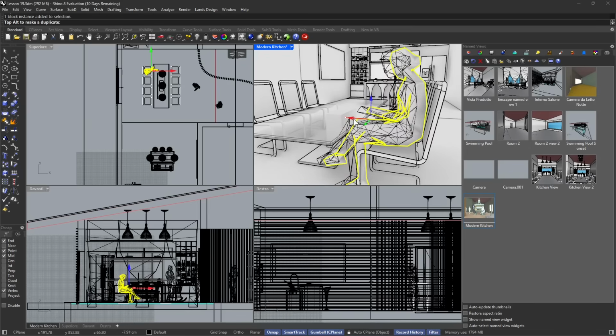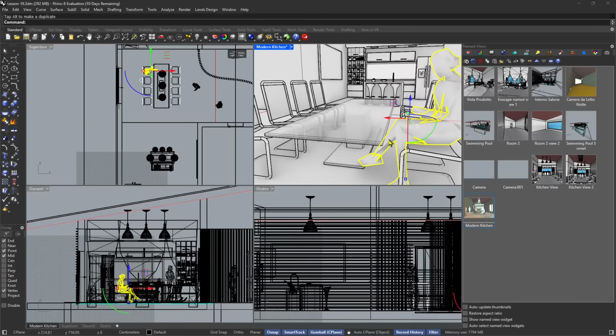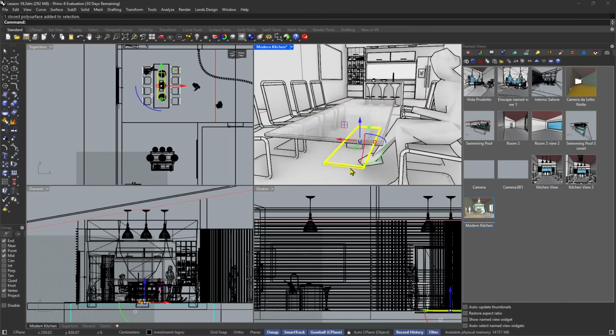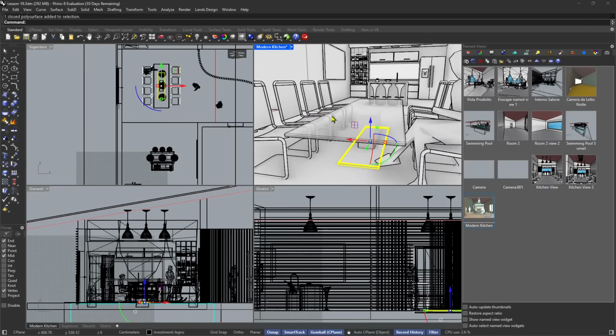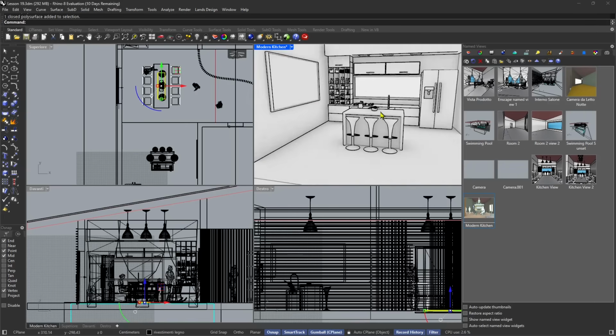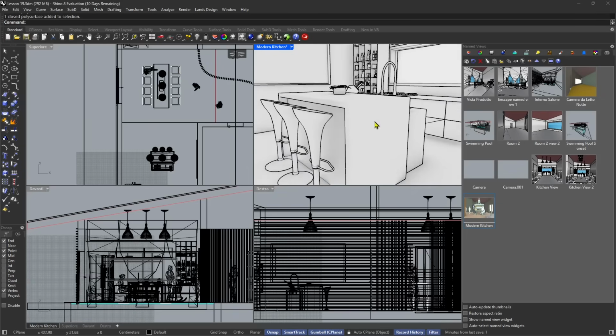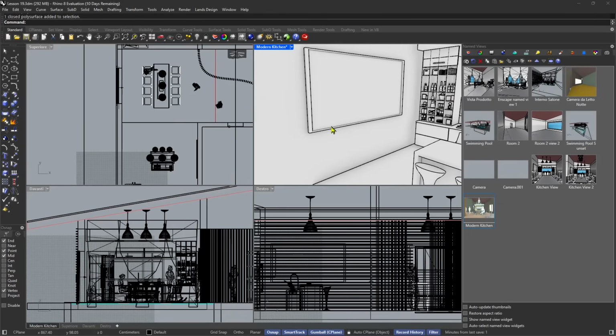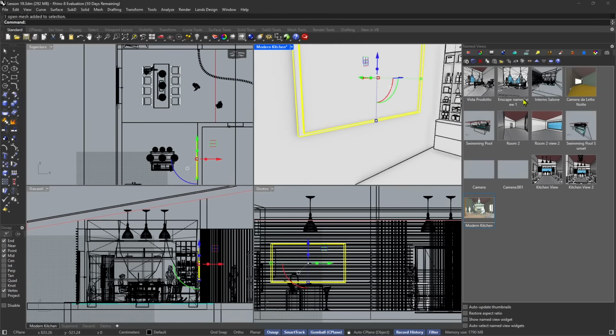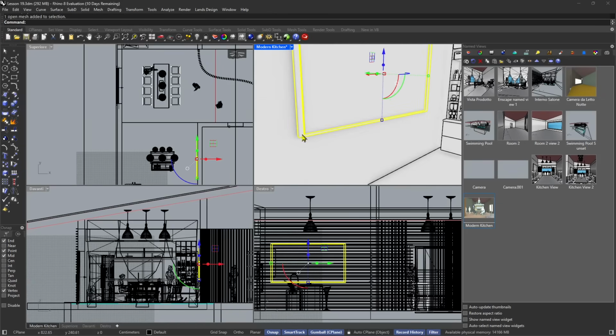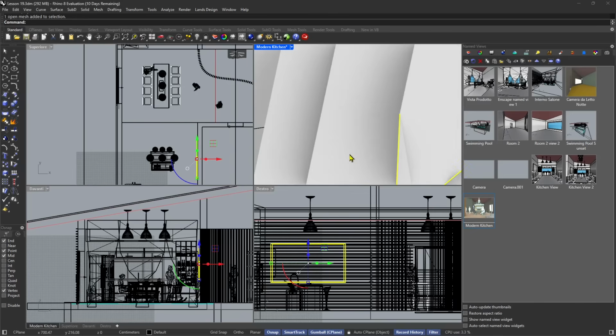So also here in the table, let me push this a little back. We added this with the modeling tools, with the fillet and the chamfer, and that's good for rendering. But sometimes when we import or when we create something, they don't always have straight corners, like in this case. So I'm just gonna pick something to show you. We can add them as an effect, just as a render effect.